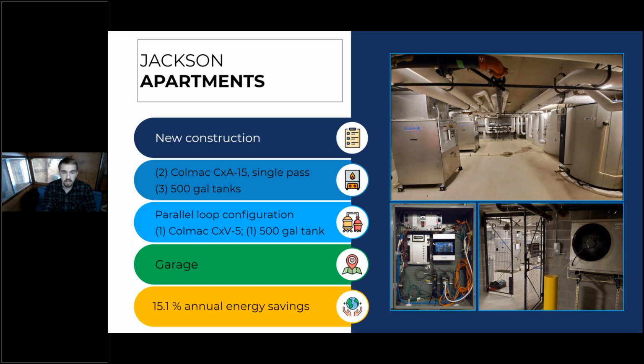So we actually have designed a parallel system with a heat pump water heater that is specifically designed to allow those higher entering water temperatures and still operate efficiently. So you can see in this bottom picture, we have this small heat pump paired with this tank right here to handle those recirculation reheating loads. And then this has a backup water heater in case anything goes down in the system. We're not seeing cold water events.